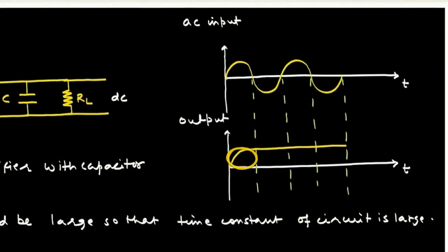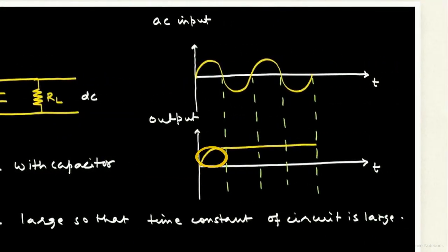As the rectified voltage rises toward its peak, the capacitor absorbs electrons, filling its internal reservoir with electrical charge. When the incoming voltage begins to drop, the capacitor releases its stored energy into the load. It physically props up the output voltage, bridging the gap before the next incoming wave can arrive.